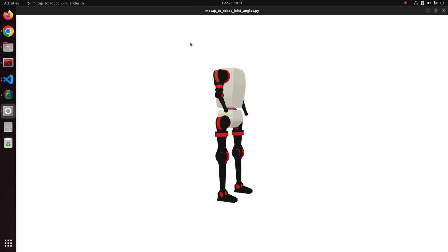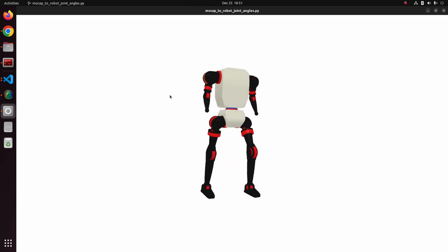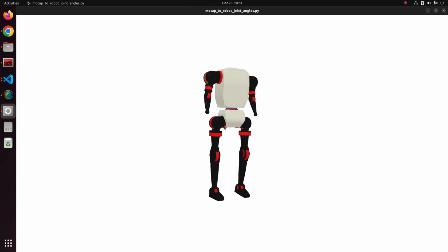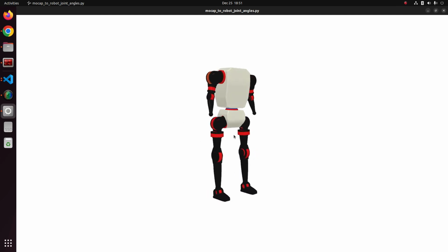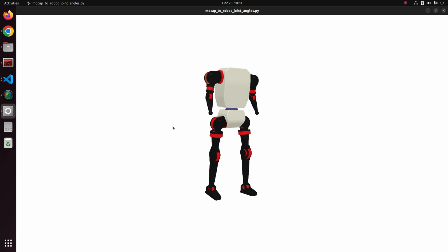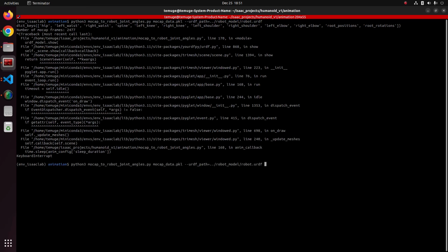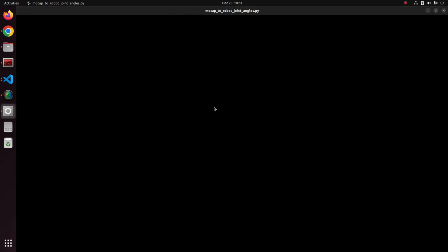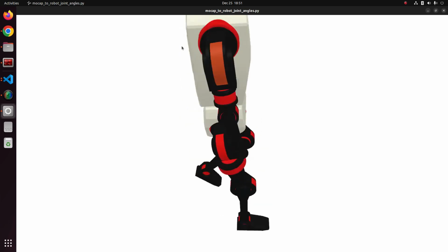And I also have a package for calculating joint angles from the 3D key points. So here are the joint angles applied to the robot. I take each rotation direction and I apply it to the corresponding motor, and it looks like this. You can see it's not very smooth and has, well, multiple walk cycles from which I have to take a single one out. So that's done simply by